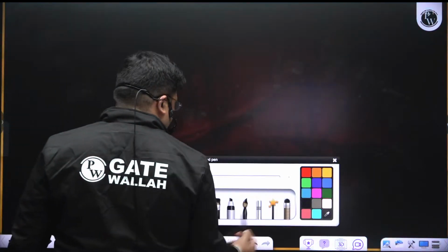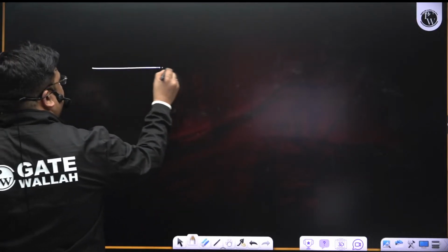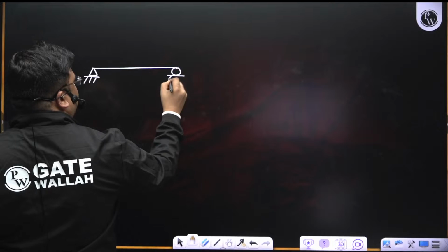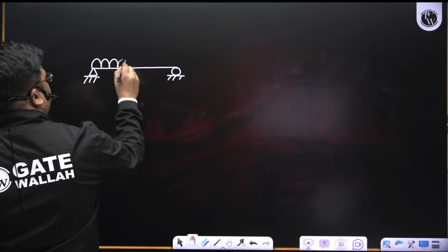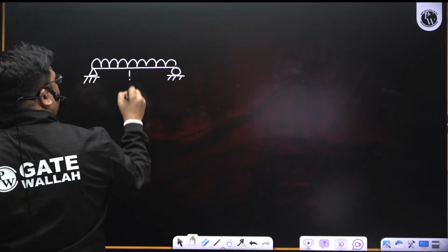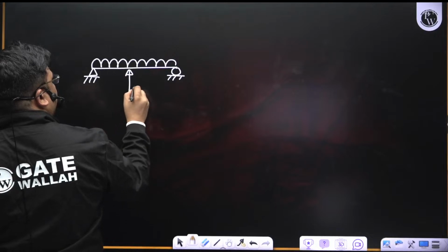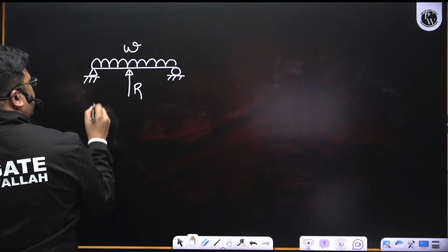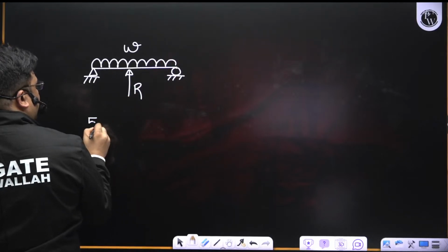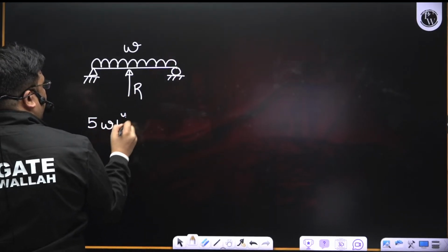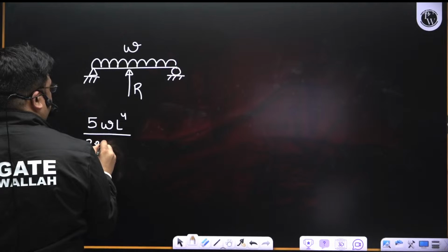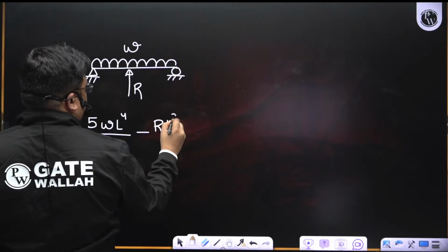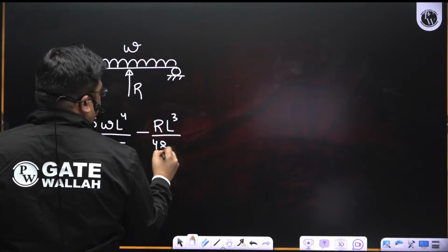Let me draw. For the beam, there is UDL acting and this reaction force acting, right? So the central deflection will be 5WL⁴ by 384EI minus RL³ by 48EI.